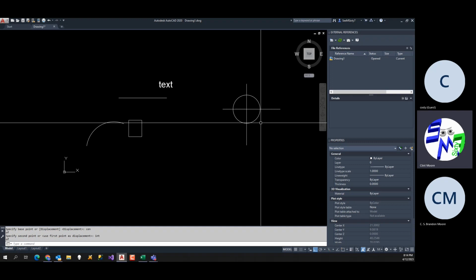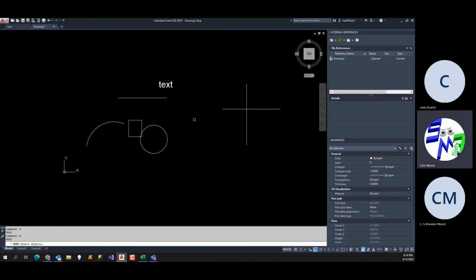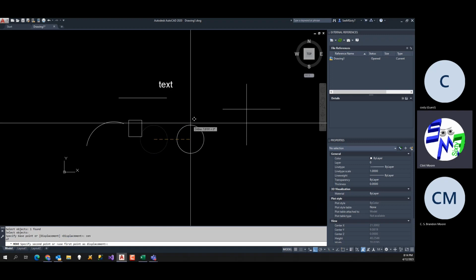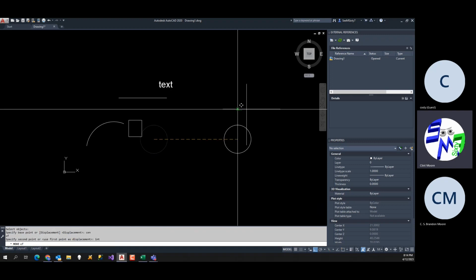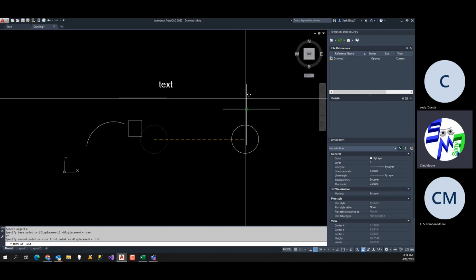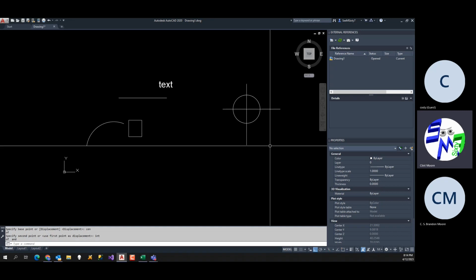All right. Now, if you notice something else, undo. If I move this from CEN of here to INT of, I just see how it's got those three little dots on it. I'm not sure if you can quite see that. There's an X showing the intersect symbol, and then three dots. That means that you have an extended intersection, as you can see what it's saying right there. If I pick here and then I get over this, it shows the intersection of those lines there.